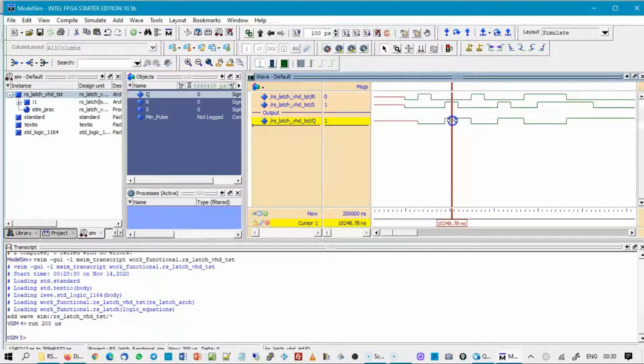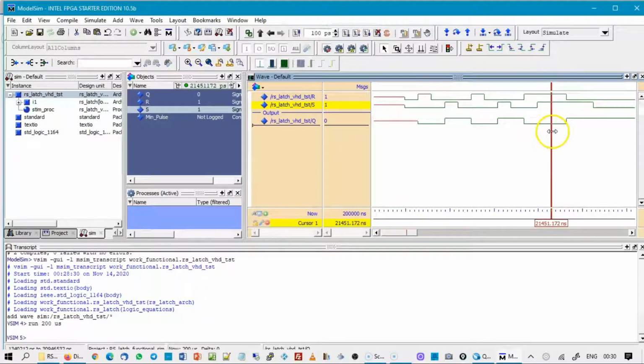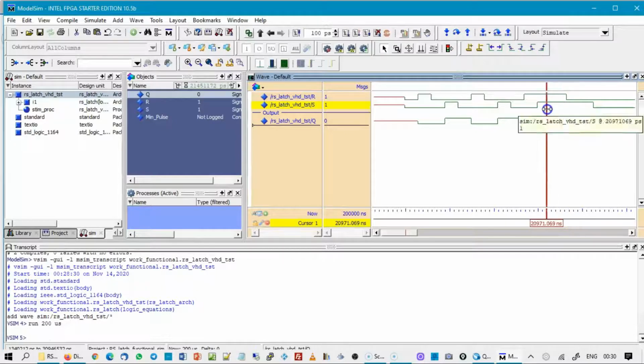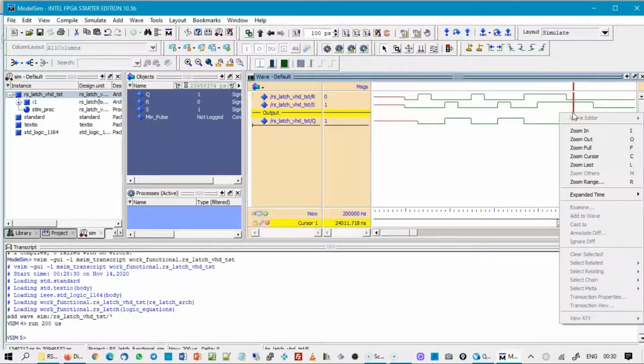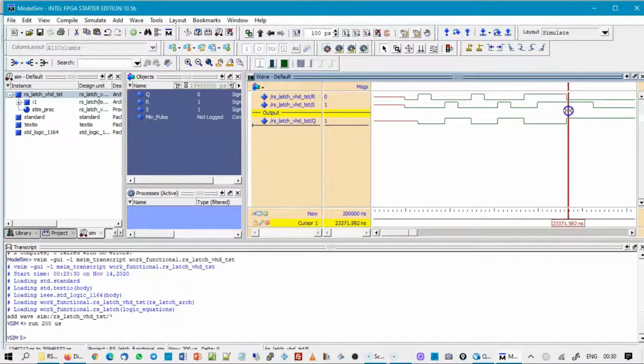You save a 1, the output, and this 1 is kept forever unless you are inputting another condition like this, save a 0, and then save a 1, and the like. And if it happens that you are 1, 1 in this simulator, you see the 0 value is kept. But in some way, when the situation clarifies, when you have again a clear order, not something like this 1, 1 that is not predictable, but when you have 0, 1, the output goes straight to 1. And that is the end result, even if you go to 0, 0 to the end.